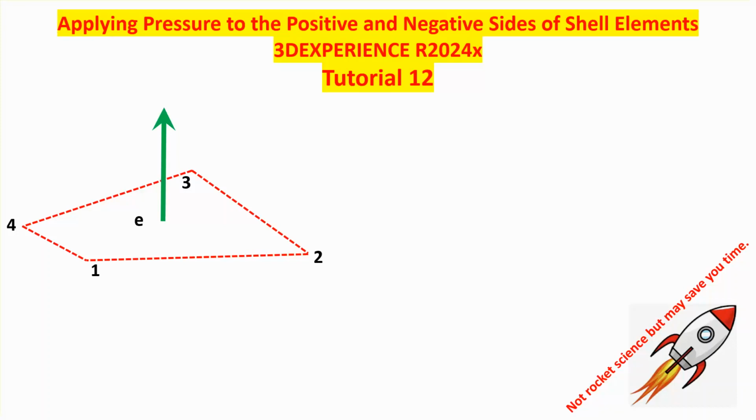But I didn't do an example. So let me remind you what happened. And if you don't know this, I suggest that you watch video 11 first. But here we have a four-noded linear shell element. And the connectivity, when you say element E has node numbers 1, 2, 3, 4, or element number E has node numbers 4, 1, 2, 3, etc. That sequence, the way you say it, and the right hand rule will give you the direction of the normal to the shell, or the positive side of the shell, and it's like that.